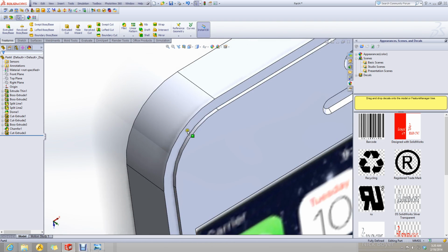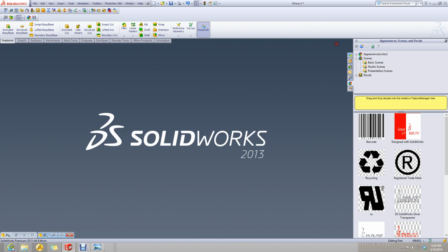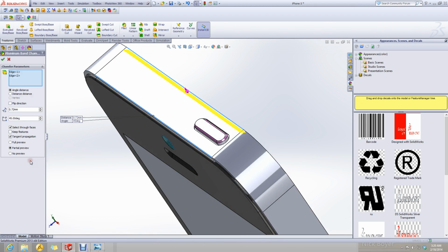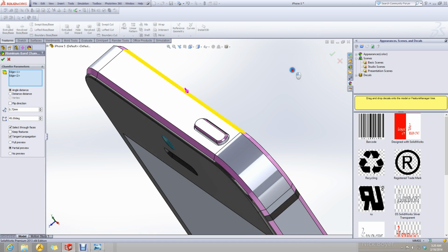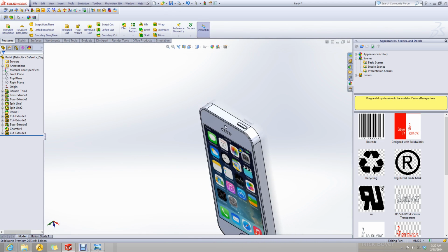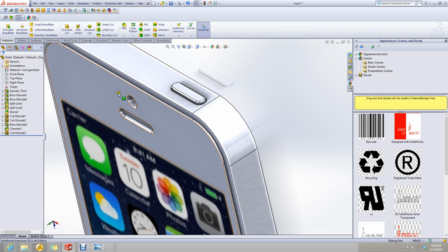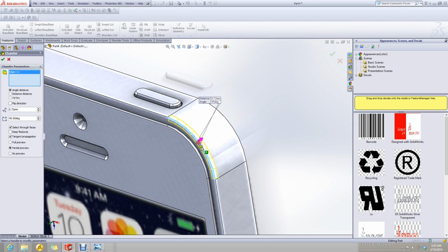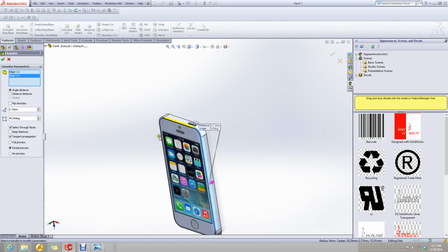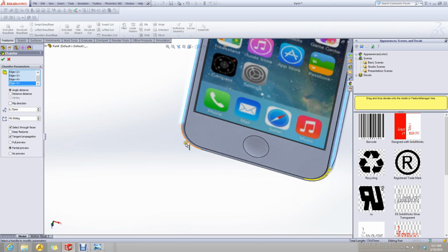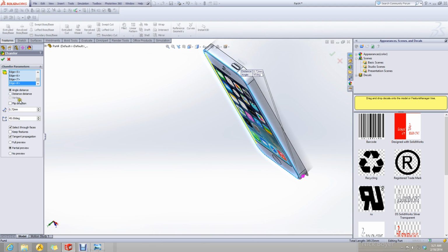Okay, let's see how much the chamfer is on this aluminum frame. We'll check the target model, check this chamfer, the aluminum band chamfer: 0.72. We are observing that 0.72 is quite typical of the iPhone. They have used this dimension in many places, with different offsets in different places. Okay, we will use the chamfer command. This is 0.72. Alright, okay, nice enough. This is 0.72.